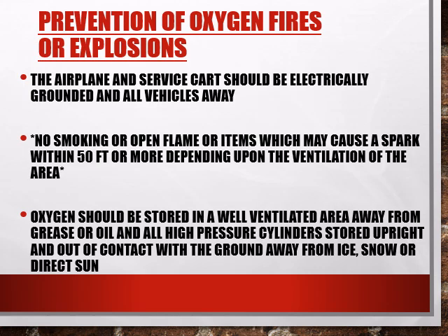Ground all equipment and remove flammable materials from the area. No smoking or open flames within 50 feet. Oxygen cylinders must be stored upright in dry, shaded, and well-ventilated areas, away from oils, grease, and direct sunlight.